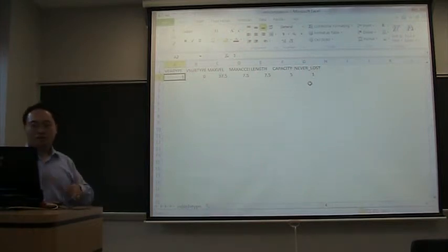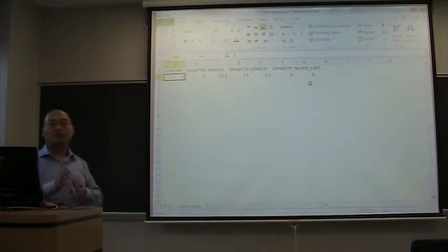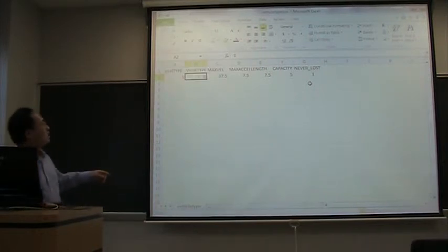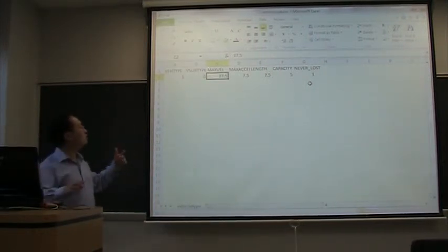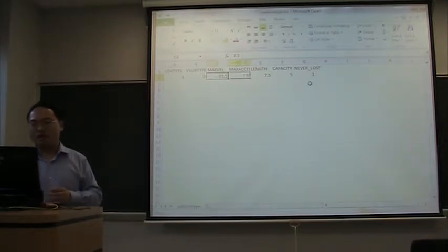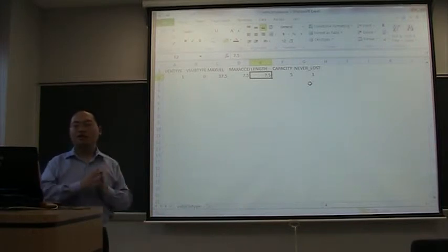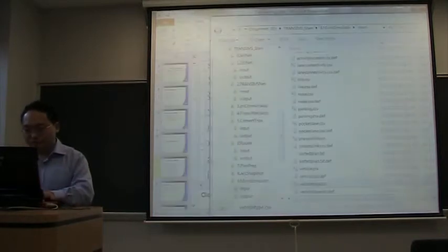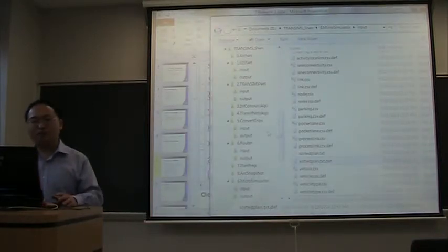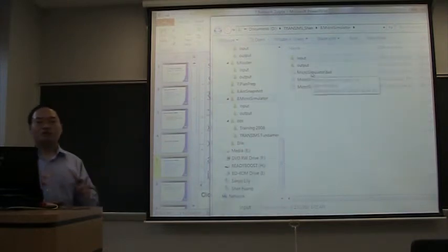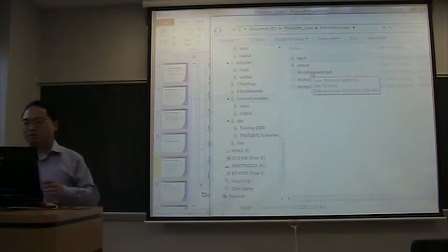In our result, if you remember from convert trips, all the trips are using vehicle type 1 and vehicle subtype 1. So I'm just defining these attributes. For example, this is maximum velocity, which is equal to 37.5 meters per second, and the length of the vehicle is defined as 7.5 meters. All of these are using the metric system. This is why I have to supplement them in the micro simulation stage, and other inputs are created from previous steps.